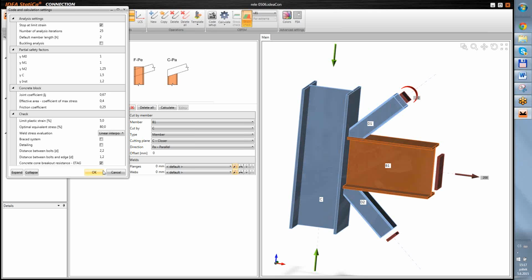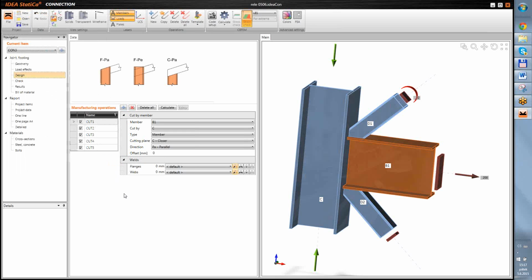And I saw in my version that on the welds there was a peak stress of 1,000 or 1,500 megapascals, and then we make it an equivalent stress, or we average it. Is it a correct model? Should it be there that you have such big stresses, although it is a peak? And the other question from customers is how can I see which forces from one component go to the other component?